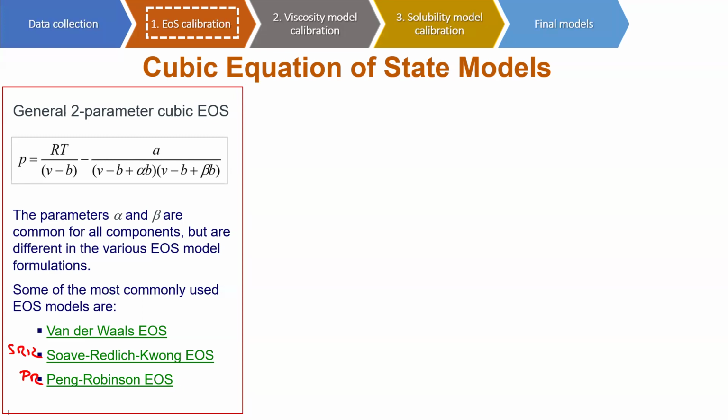There is no clear advantage to using Peng-Robinson over SRK. But we standardize to use only Peng-Robinson in Petrobras because it makes the comparison easier between different fluids or different equations of state. In a big company, all the time you need to be concerned about comparing approaches, homogenizing different approaches, comparing results of different fields, and learning from a specific field in order to get ideas to apply in another greenfield.